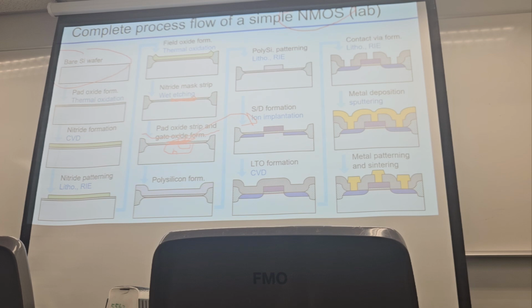Okay, so then we can jump here to form the isolation layer prepared for the two terminals. So we can cover the whole structure with dielectric material, and then etch this region, right?